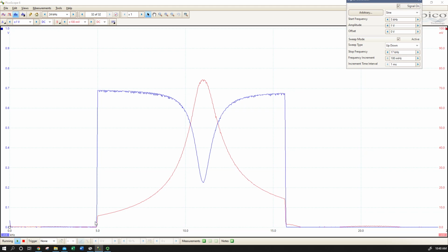And if any of you have taken chemistry and are thinking this sounds an awful lot like collecting multiple spectra with optical spectroscopy like infrared, it's following the same principle that fast Fourier transform is used to do optical spectroscopy, as well as just frequency sweep spectroscopy. Basically, in both cases, we're looking at the frequency of something. In our case, it's the frequency of a sinusoidal electrical signal. In optics, it's going to be the frequency of light, both measured in hertz.